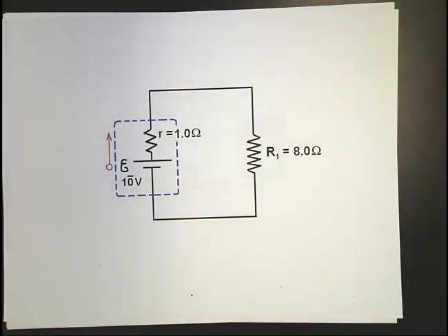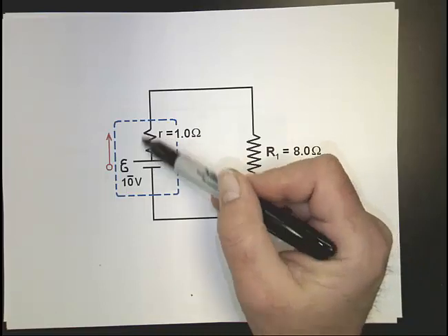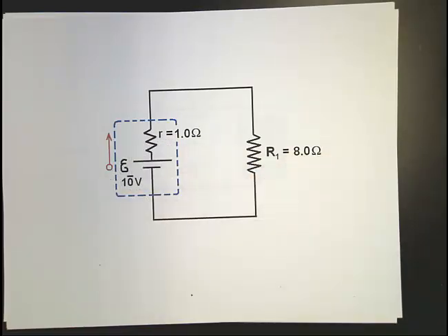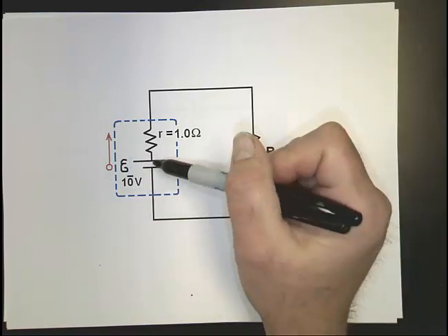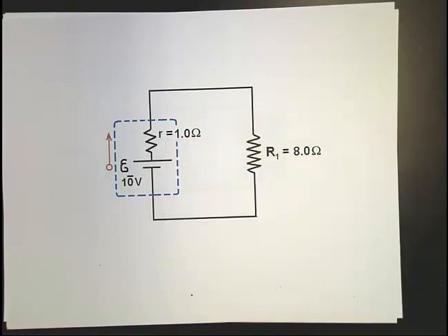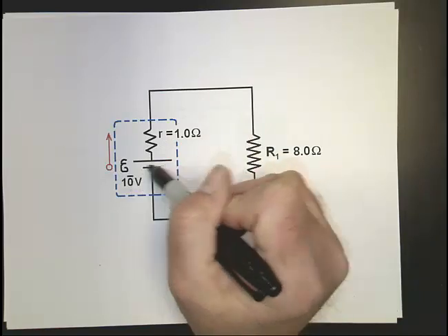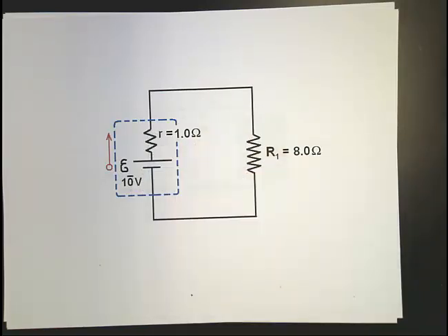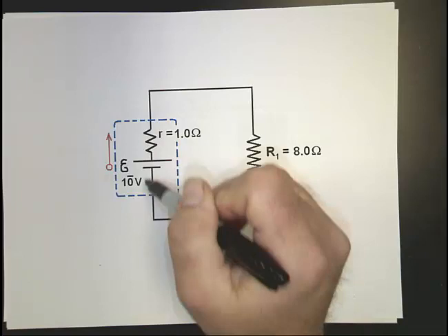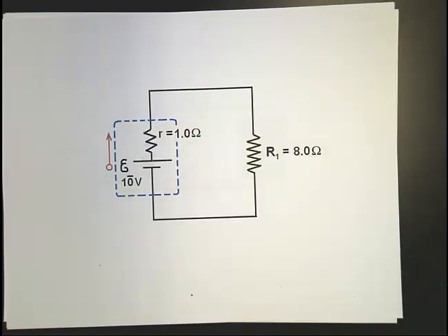One more topic before I move on to the other Kirchhoff law is the idea of a battery with internal resistance. Because real batteries are not perfect. What will happen is the battery has a kind of an ideal EMF of, say, 10 volts. And there's also an internal resistance in the battery. Now we represent that as showing like the perfect battery with a tiny little resistor attached to it. So the blue dotted line represents the battery, the Duracell, and what's inside is kind of a representation of what's happening. It's providing us with an EMF of 10 volts, but there's also some internal resistance.